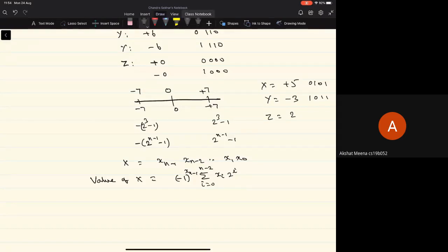And if you want to perform the subtraction operation, how can one do that? So you'll quickly realize that if you want to perform the addition and subtraction operations on the sign magnitude form of the signed integers, it turns out that is a fairly complex sequence of operations that we need to carry out. Therefore, this sign magnitude form is not really suitable for performing the arithmetic operations on the signed integers.